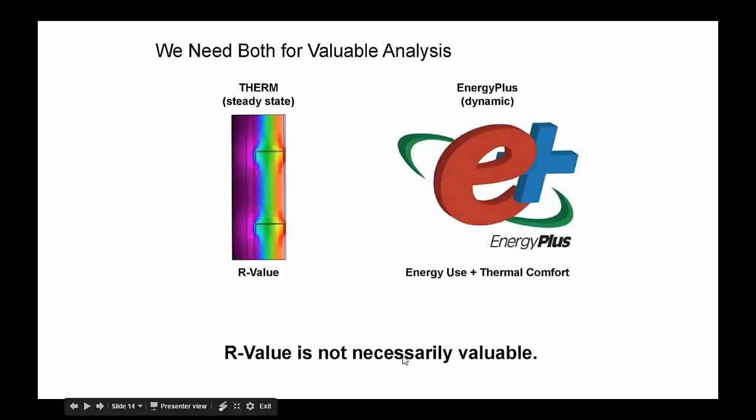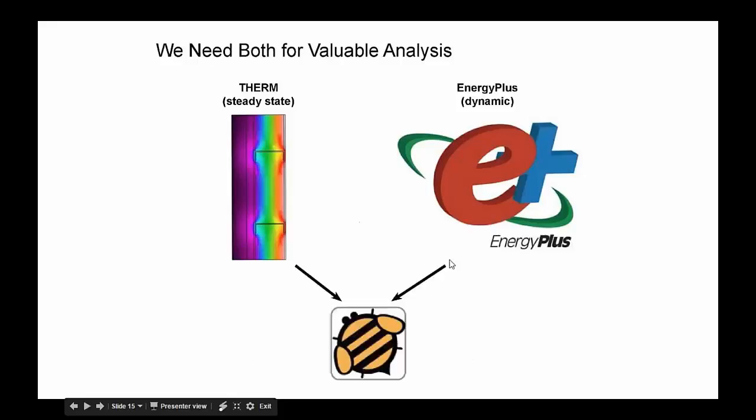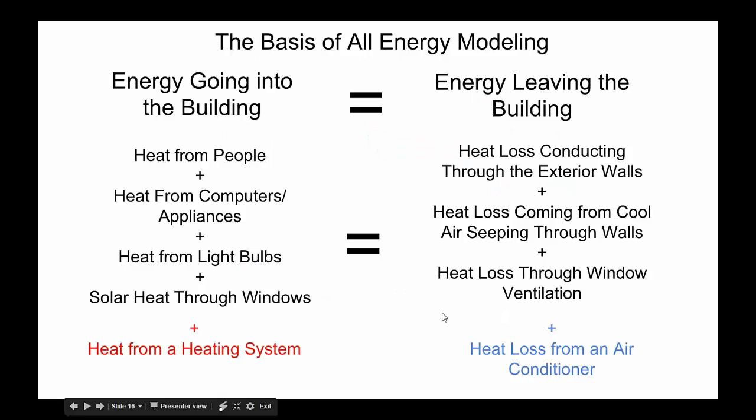This is just saying exactly what I said before. Our value isn't necessarily valuable. You really have to run it through an energy simulation to understand what exactly is the value that's delivered at the end of the day. And we're using Honeybee to bring these two together. So Honeybee, as you saw in the diagrams in the intro, is an interface for both of these things, and so it allows us to more easily bring the results from THERM, put them into EnergyPlus, and get out measures of value.